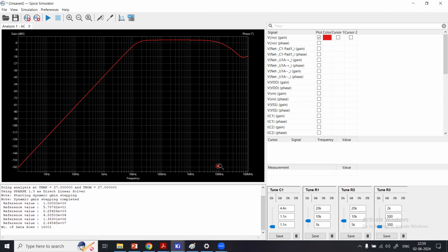So this is how you are able to tune the response of the filter. But this is like 10 megahertz. After 10 megahertz, your gain is dropping down. But so far, you can see that it can filter with a constant gain amplification all signals from like 20 kilohertz up to 10 or 8 megahertz. So that's good. Okay, so we'll keep it like this.